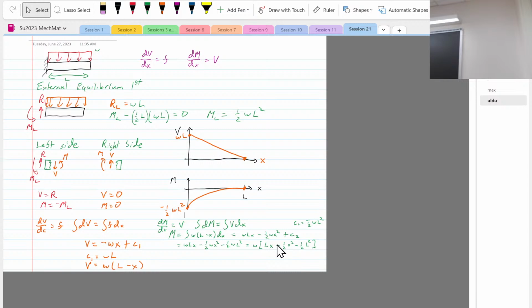So, can a bending moment apply? A bending moment is going to be something where you get no shear stress, you just get sigma, right? That's what it said. It's true, though, that you can have a shear force in bending, due to the shear force, which is related to the bending moment when we do the derivation. But for a bending moment, you're going to get a normal stress, a bending stress. For shear force, you have multiple ways that you get it.